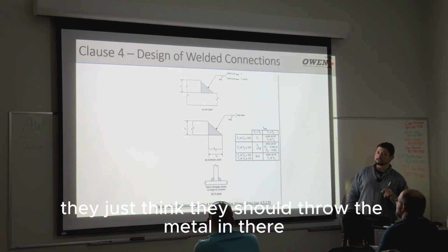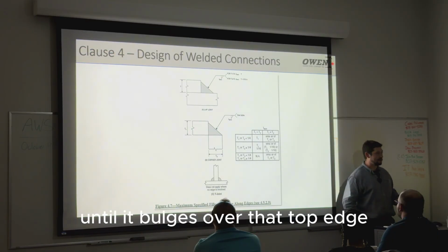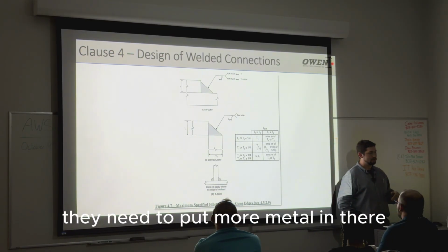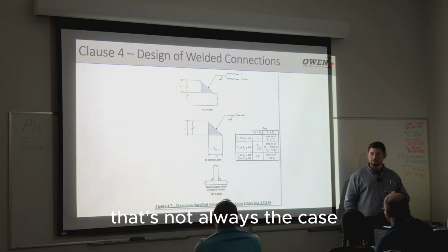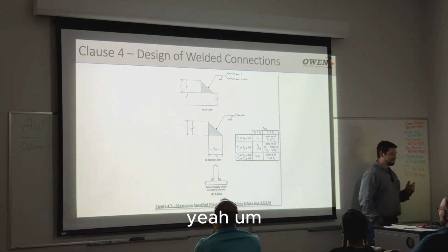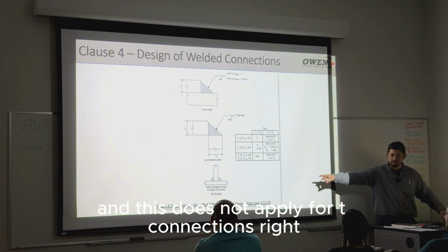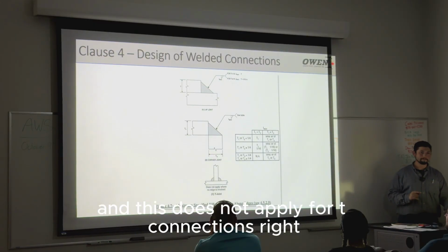A lot of people just think they should throw the metal in there until it bulges over that top edge, and then whenever it goes over the top edge, they need to put more metal in there. That's not always the case. Grinder for days. And this does not apply for T connections.